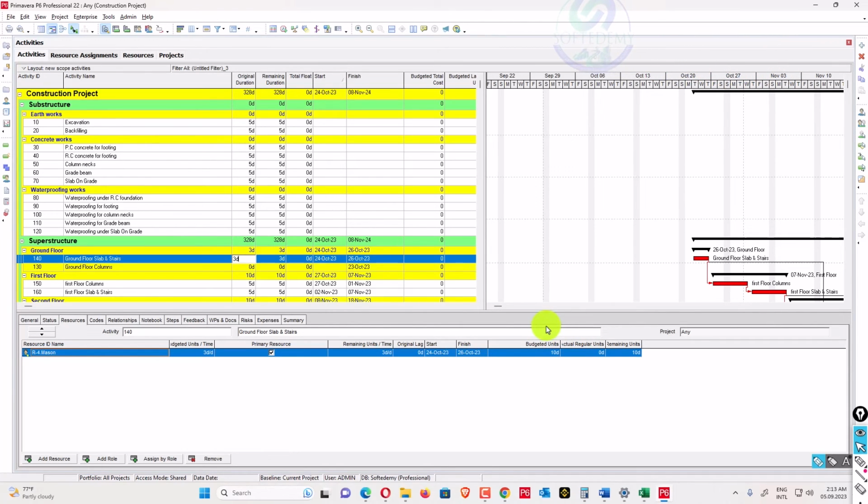In some cases, maybe working in one place, decreasing the days, applying more crews and increasing manpower, there may be a decrease in productivity rate. So you can divide it by 1.15, 15% or 10%, as your productivity rate will be decreased. So your budget units may change at that stage, but your total budget units should not be changed. If you want to change that, there will be some coefficient, like you can multiply by 1.10 with your total budget units, so your budget units will be increased for the remaining activities of the project.